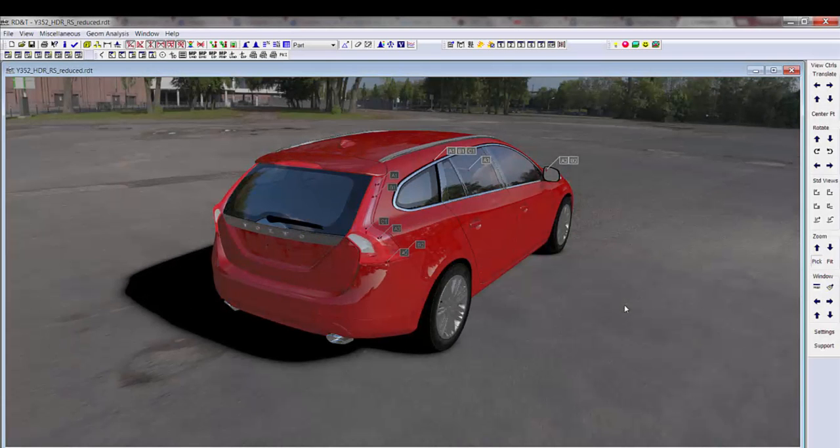Geometry assurance is about analyzing the effect of variation, improving the robustness, which means decreasing the concept sensitivity to variation, and knowing what tolerances to tighten when necessary. Tolerances are the key to mass production, but tight tolerances means high cost. If we can improve the robustness of the concept, we can create better quality without increasing the cost.